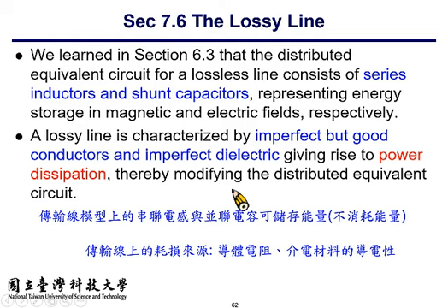transmission line conductor. The other mechanism is the conductivity of the dielectric material that separates the two conductors of the transmission line. As you already know, most transmission line configurations comprise two separate conductors, even though this is not always true, except optical fiber, which contains no conductor, and the waveguide, which contains only one conductor.